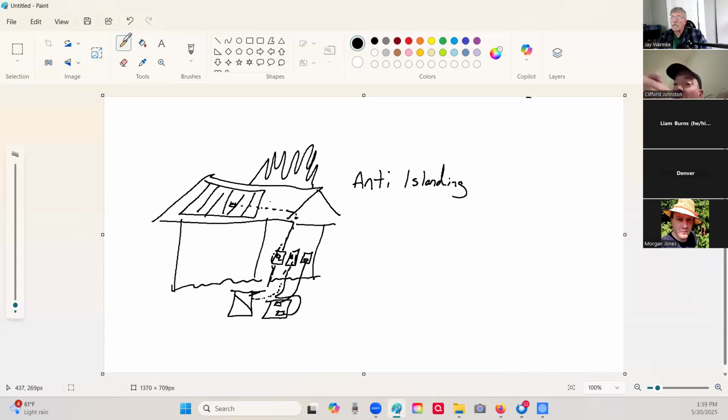So a fireman climbs up on the roof and he chainsaws through the roof to vent, and he hits this wire that is energized at 600 volts, and he dies, right? Bad idea. He thought there was no electricity in the building. He just cut through a live wire and he just died. So in 2014, the code said, hey, when you turn off this AC disconnect, we effectively want this to shut off at the array.